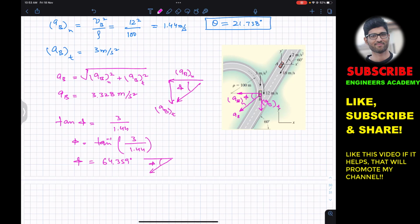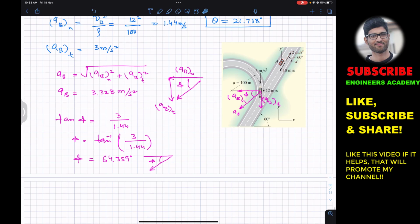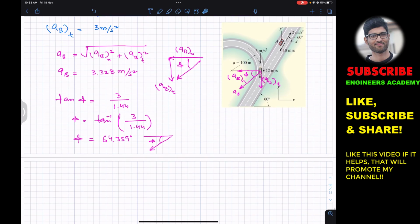And we know that the acceleration of car A is 2 meters per second square, and it is making 60 degrees. So now we are not going to solve it by the graphical method. We will draw the diagram not up to scale, but we will use the sines law and the cosines law to find the acceleration of B relative to A. Again I will use the same method.